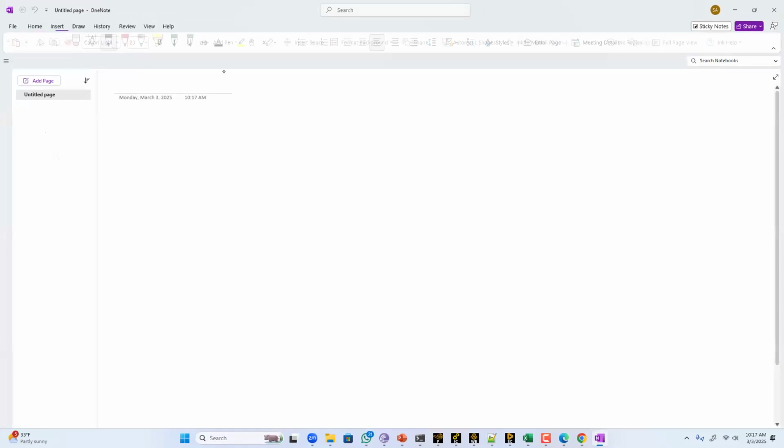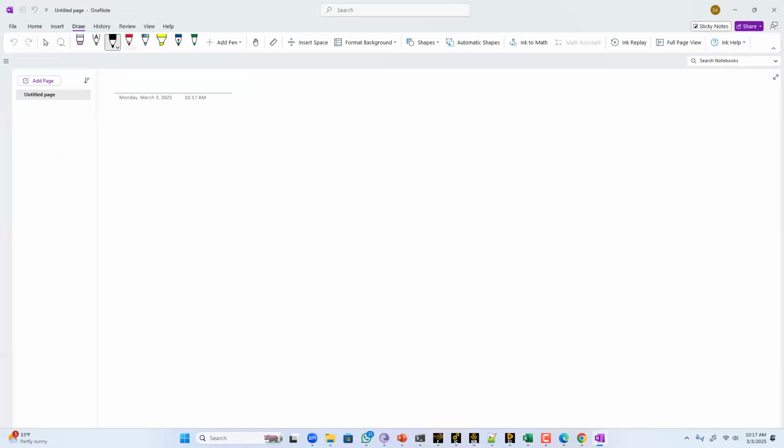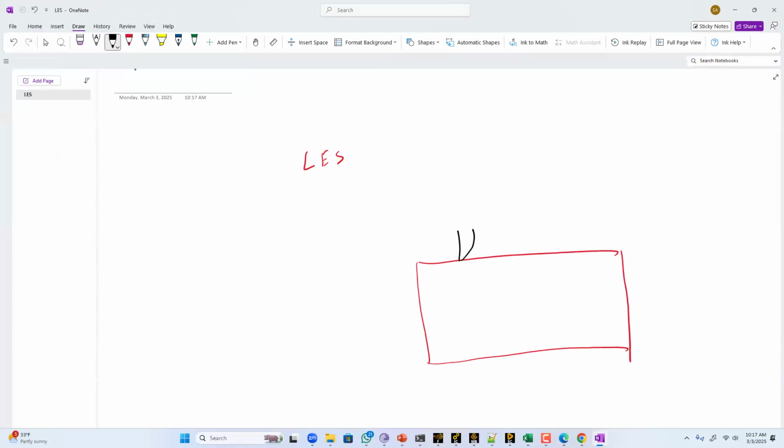Okay. LES is solving everywhere with the LES. Okay, so that means large eddy simulation. But the problem is that, for example, take this body. Okay, let's say this is similar to the MS body. In this type of case, if there's a boundary layer here, the boundary layer has very small eddies. If you talk about the eddies here, after flow separates, the eddy size will be of this much. But here the eddy size is very small.